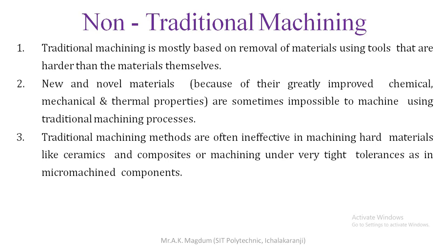Otherwise, as I already gave the example, if the tool is aluminum and the workpiece is mild steel, the material is not removed under traditional machining processes. So how can you remove the material in that condition? The only way of machining is non-traditional machining. So these are the various limitations of traditional machining, which we can overcome only with the help of non-traditional machining.